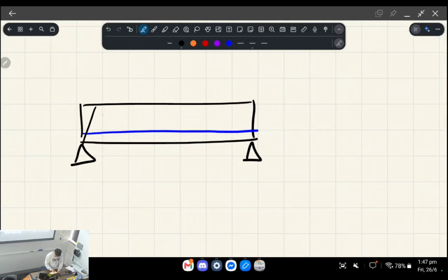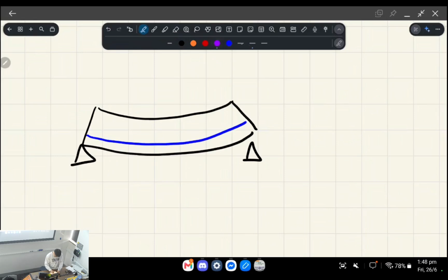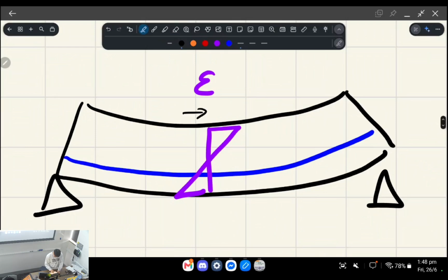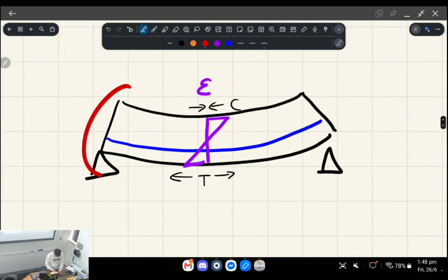As this beam bends like so, using engineer's beam theory, we want to say that the top side is in compression and the bottom side is in tension, right? However, we've basically assumed something that I haven't explicitly stated. We've assumed that the concrete and the steel can essentially shift perfectly in line with each other, right?